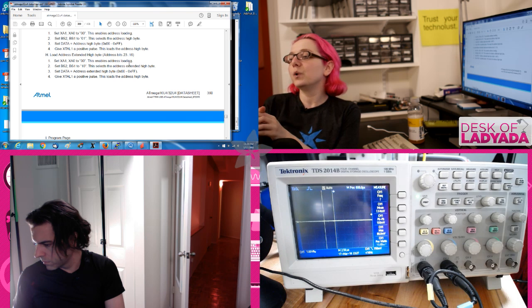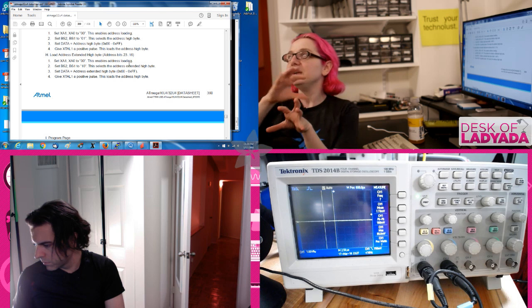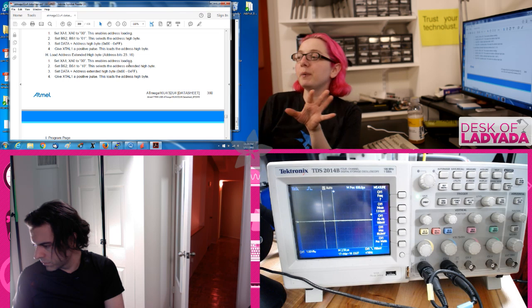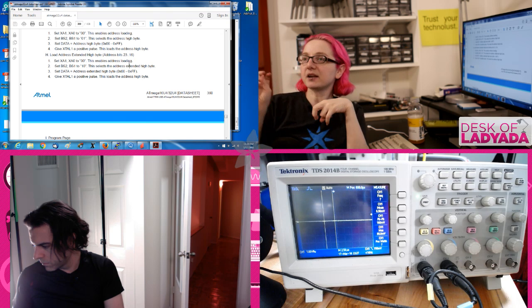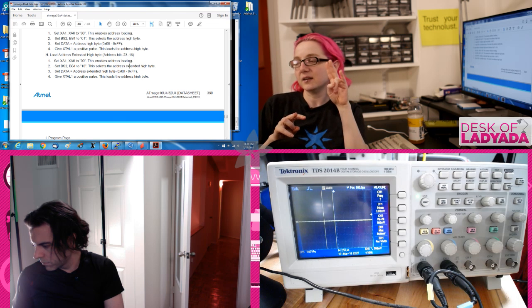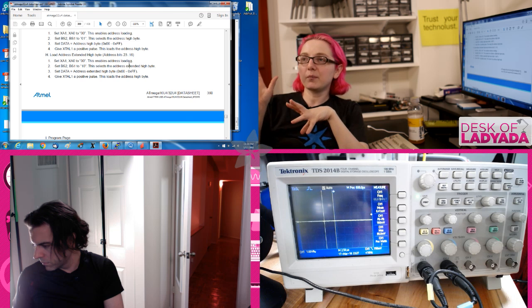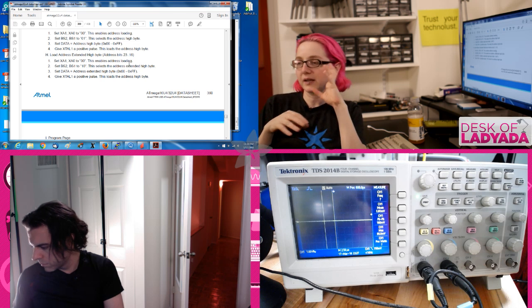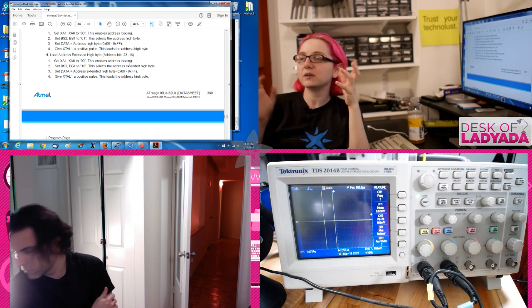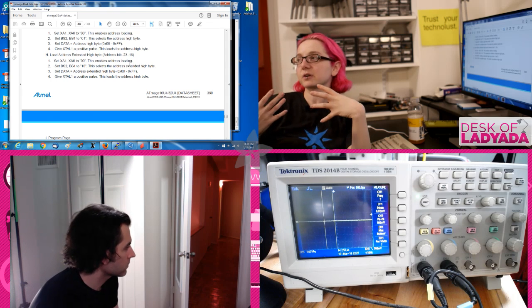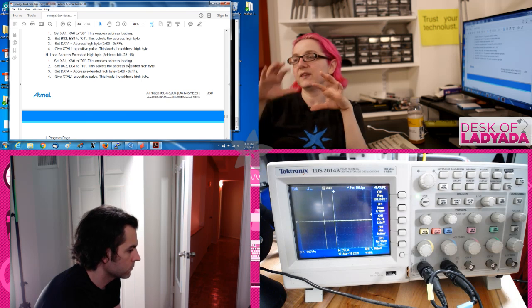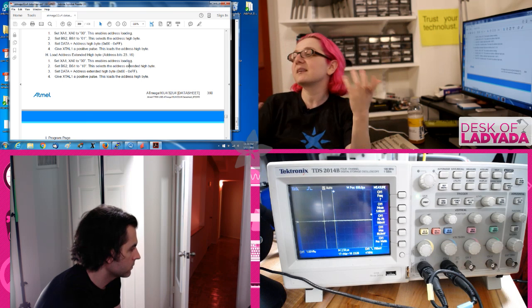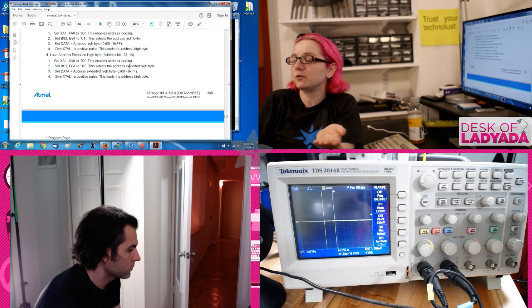However, each SPI Flash chip manufacturer then goes totally bonkers with special commands like page write and protect chip and fast erase and scramble and give me the temperature and random entry. They'll come up with special extra commands. So even though they always support the JEDEC standard, then they kind of go crazy, because that's how they compete. If everyone had the same command set, it would just be pricing.